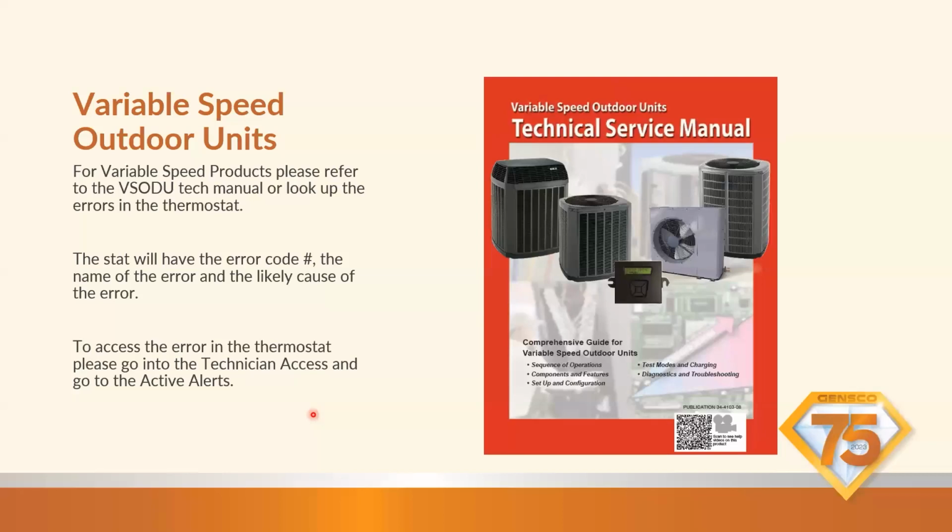They're going to give you where to look. These are really helpful. These thermostats, they kind of do your work for you sometimes. On the variable speed products, I would recommend whenever you're getting an error code at the outdoor unit, you go look at the error codes on the thermostat, because that's going to give you the details.